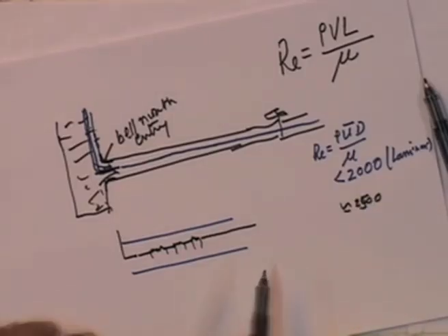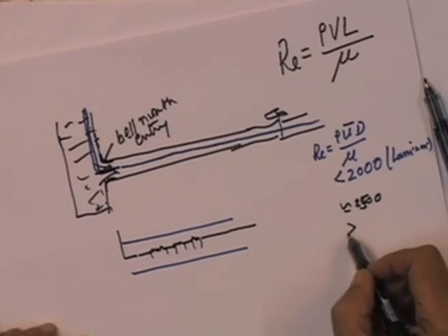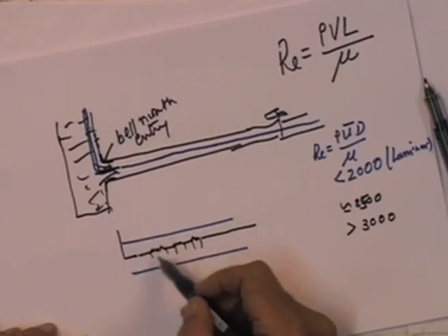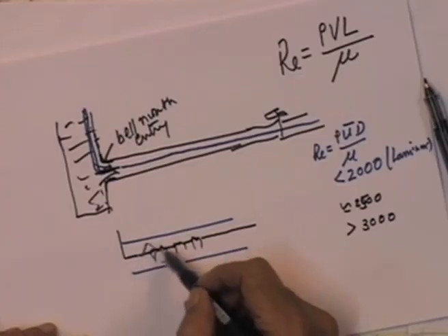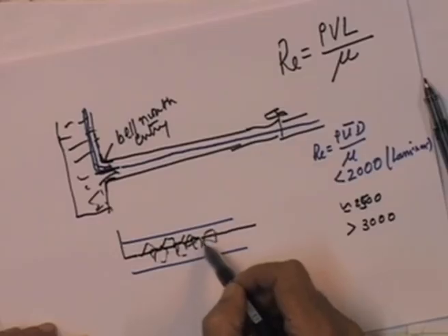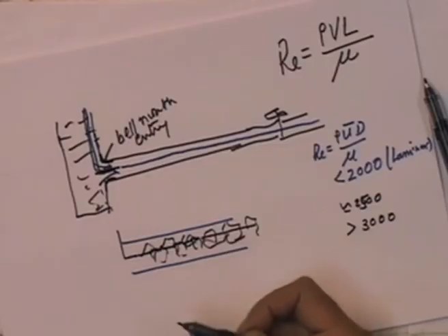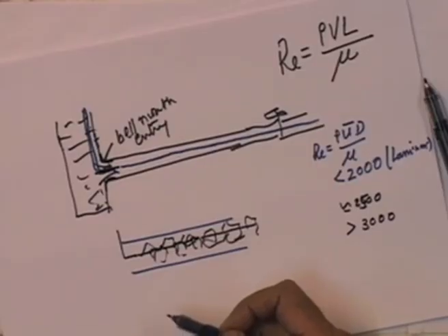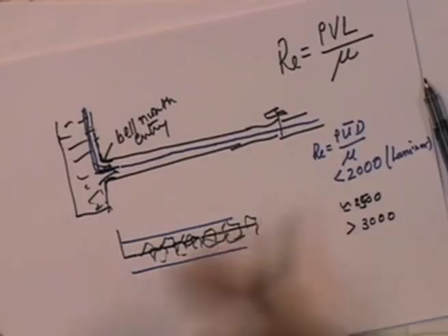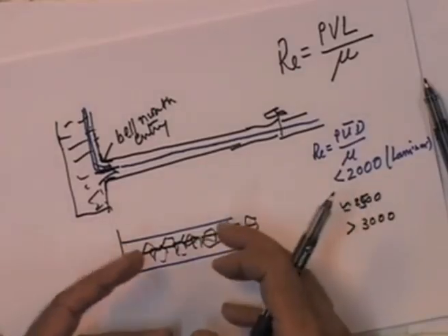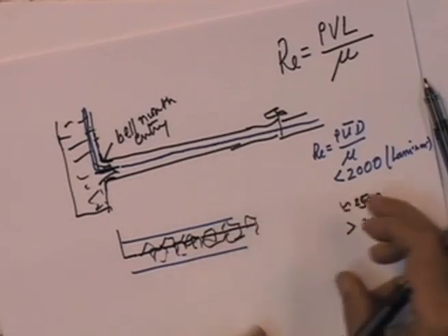But certainly, when the Reynolds number was greater than 3000, he found that the entire tube would get engulfed by sinusoidal motion, or what he called sinusoidal motion, or really random turbulent vortical motion, and the dye would completely mix out into the surrounding water, and you had colored water coming out.